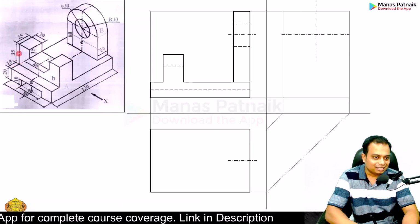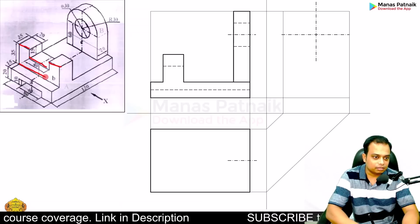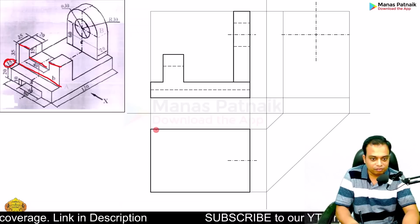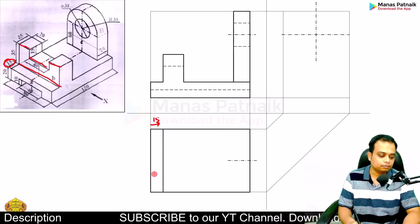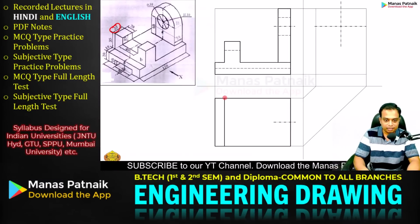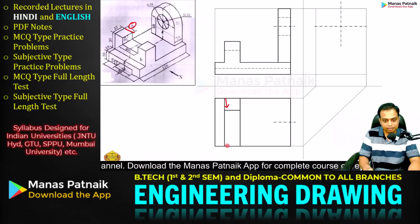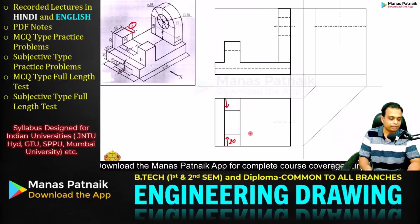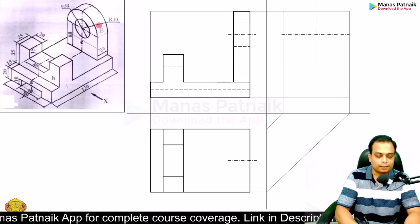Secondly, if you watch this edge over here, the projection of these three edges will be this, isn't it? At a distance of 15 from the left, draw this. Done. How far? This is 25. So at a distance of again 25, draw. Done, sir. This is 20. Come forward by 20. Come forward by 20. And then from here again 20. Do it. Done. What's left? Sir, this is left. This profile.